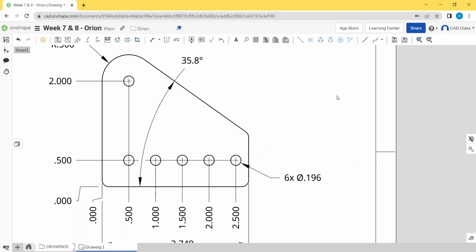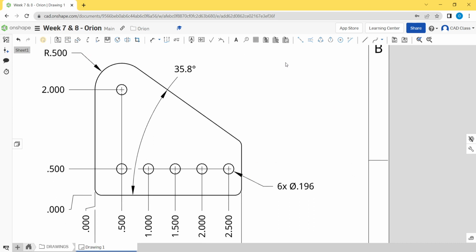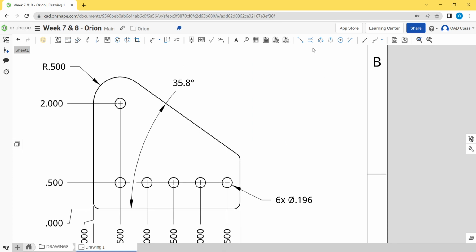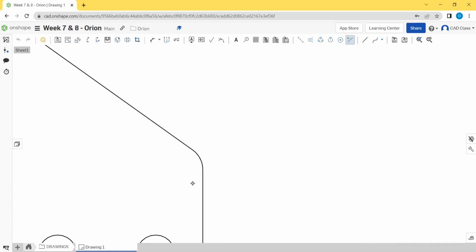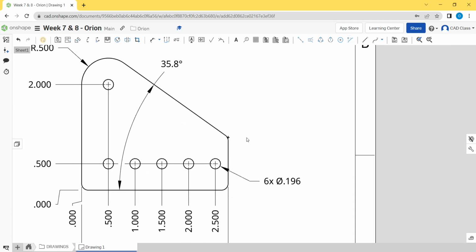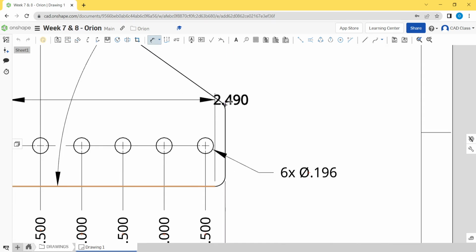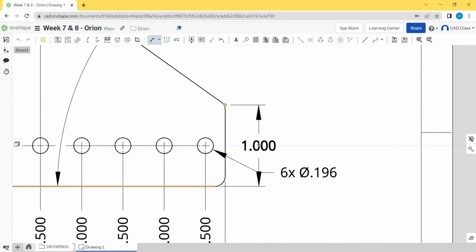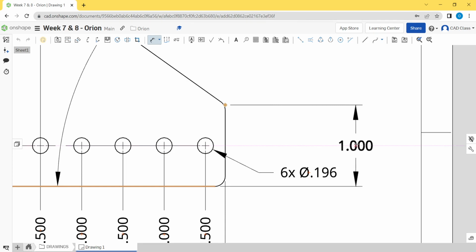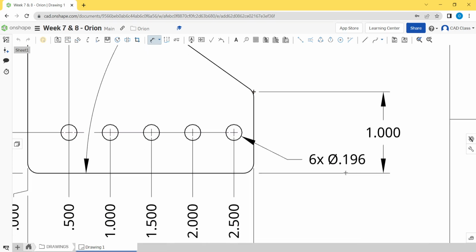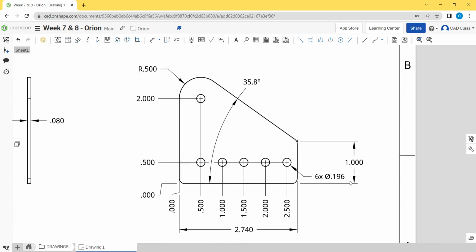So let's try to add some construction geometry to accomplish what we're doing here. What's this? Virtual sharp, that's what we want. Okay, so it looks like if we just select these two lines, it'll just add a point for us. Then once we have a point there, we can just dimension it to the point, and that accomplishes what we need to do. So there is a way to do it. You just have to add that point in there manually first. Like I said, I've never actually done that before, so you learned something new.